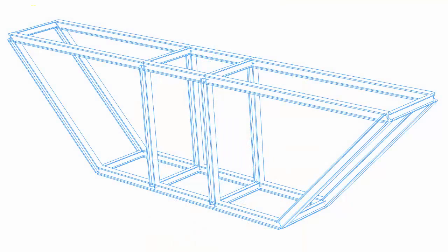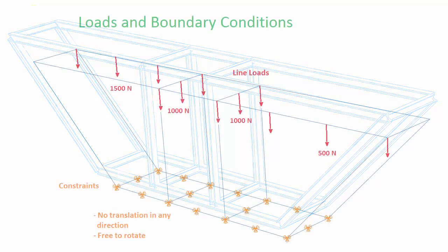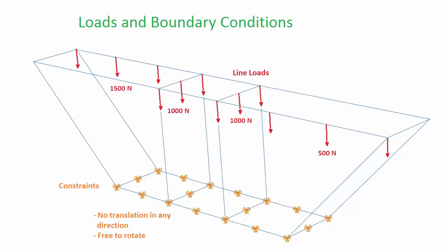The structure consists of two-dimensional frames which lie parallel to each other. They are connected to each other by horizontal beams at all of their nodes. I shall refer to these as the cross-bracing or cross members, even though they're not in the shape of a cross as the name usually implies. The structure is fixed at the bottom.